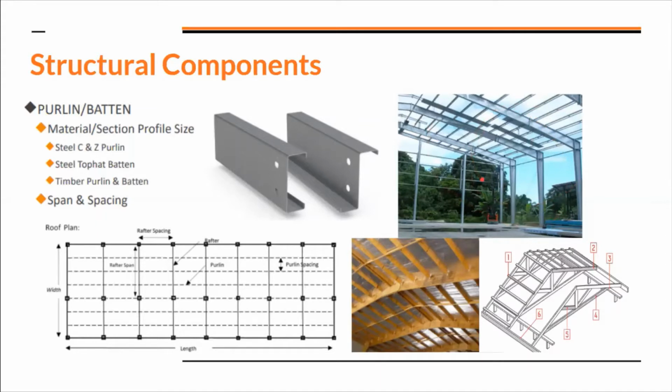When we do our assessment, although we understand that the foundation is overall where the forces will be ending, we believe that this section of the roof is the most critical section of the roof, the rafters and the purlins. So when we do our assessment, we look at the deflections of the purlins, we look at the deflections of the rafters, and we see how critical the additional panels are onto this upper structural system.